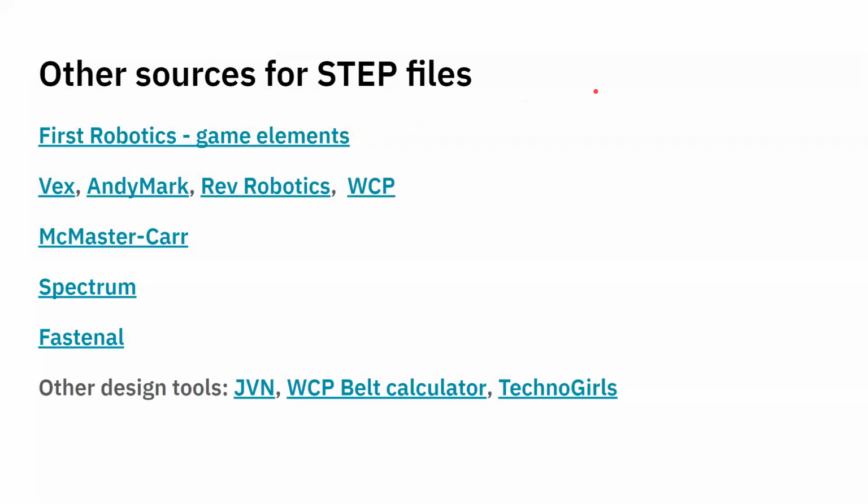Now, in terms of documents, you can see I'm referring to step files. And step files are a format that you can use to share 3D models with different things. And if you've ever done 3D printing, you may have encountered STL files. So STL files, stereolithography, those are files that are great for sharing 3D printing. The problem is that you can't really edit them very well, whereas a step file is an actual 3D model.